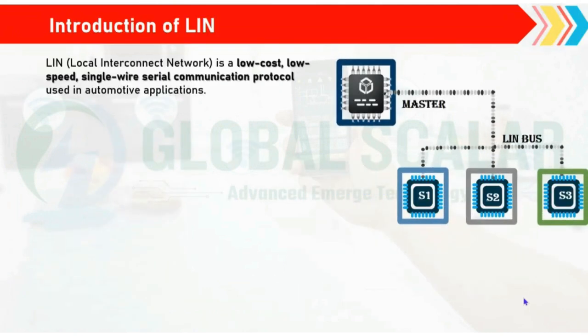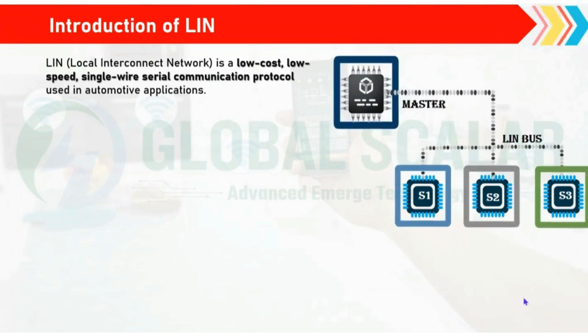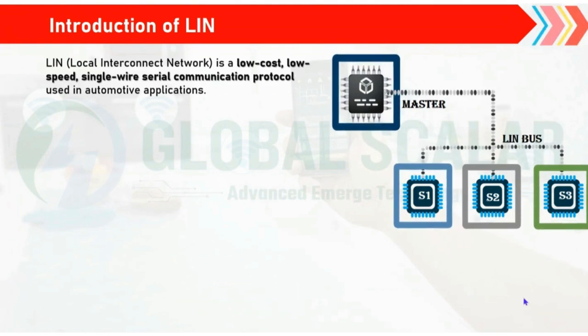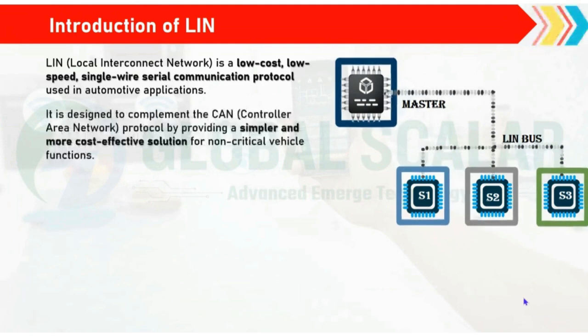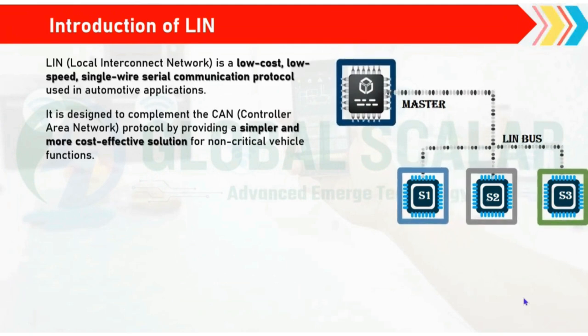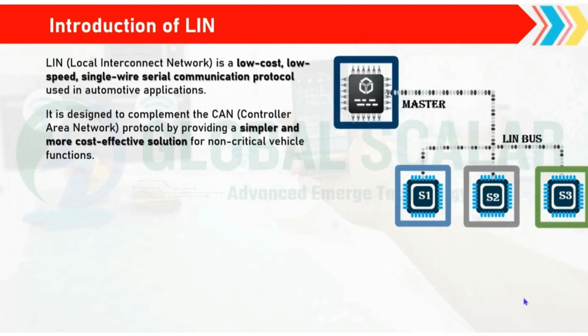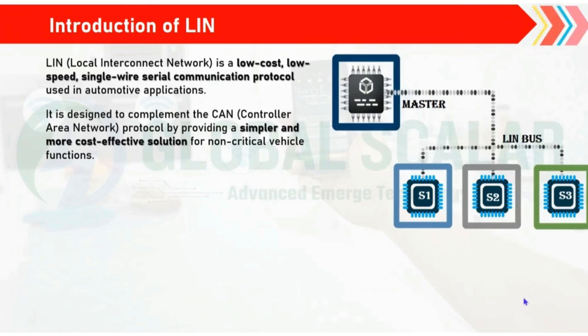Coming to the introduction of LIN, LIN is the Local Interconnect Network protocol. It is a low cost, low speed, single wire serial communication protocol used in automotive applications. It is designed to complement the CAN protocol by providing a simpler and more cost-effective solution for non-critical functions.